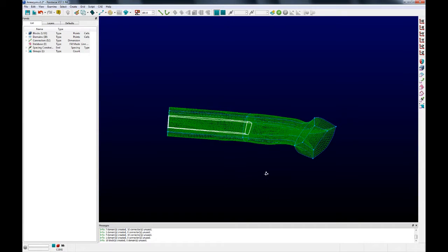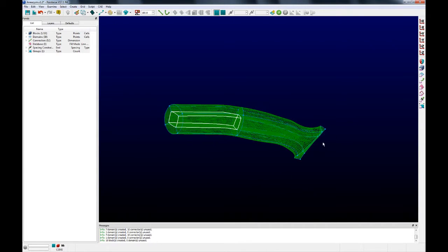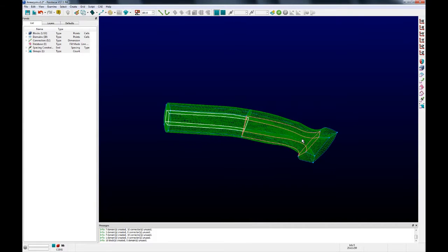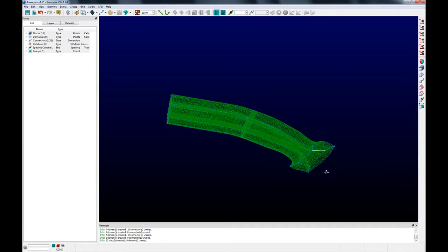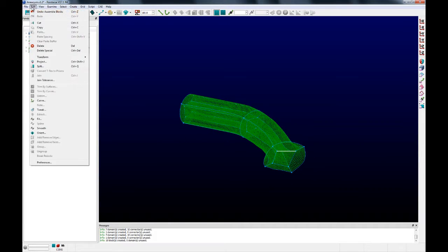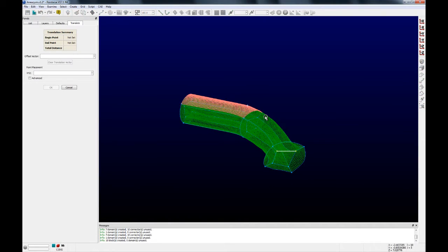The next step that we need to do is going back to that topology I sketched out at the very beginning. We need to provide some 3-dimensionality for this junction here so that this artery can connect to the adjacent artery and the aneurysm. So in order to do that, we're going to select this curve and transform it and move it around to give it that 3-dimensionality we wanted. So to do so, we go up to Edit, Transform, Translate.